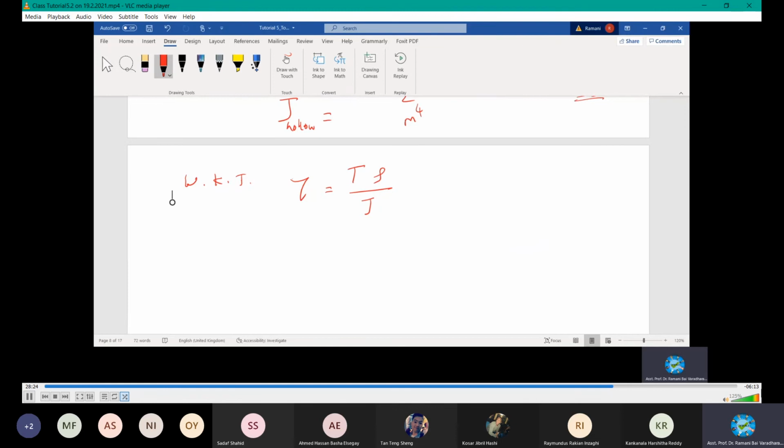Now, for the allowable, the shear stress should be equal to the allowable stress in this case. You are given it. What is that value? Better write down 100 megapascals, correct? Let me substitute. I need torque, so I separate it out. We do it one by one, since you are asked for two things. I make it a solid, torque of solid.